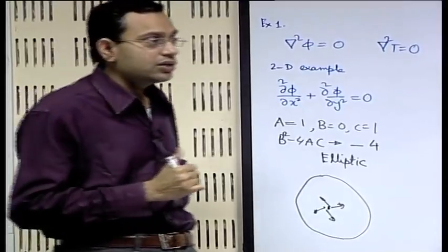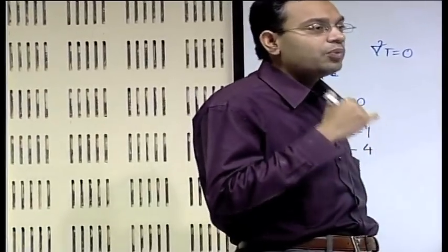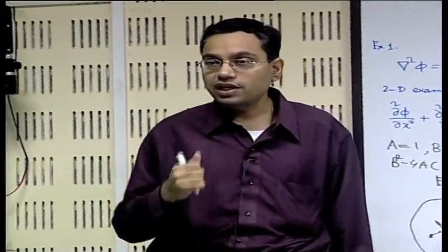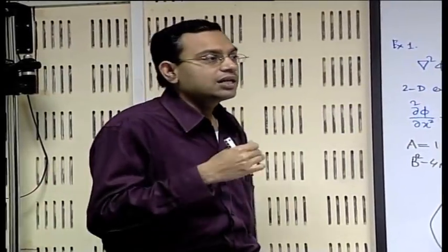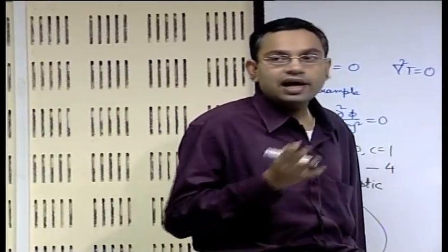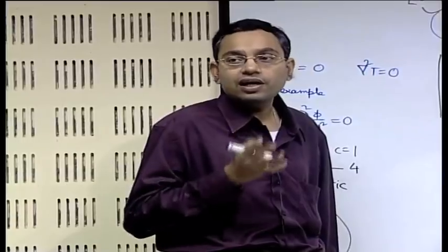That is very important. So, this is one of the very important physical meanings that is being conveyed by the Fourier's law of heat conduction, that when you have a thermal disturbance, the thermal disturbance propagates towards all possible directions at infinite speed.